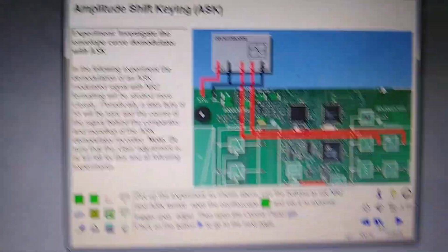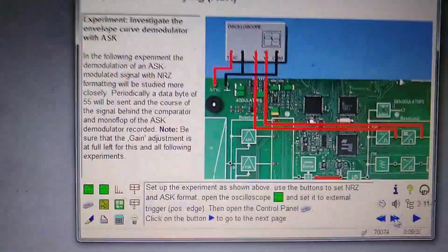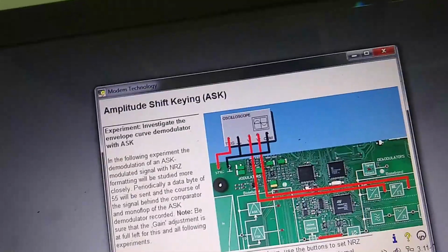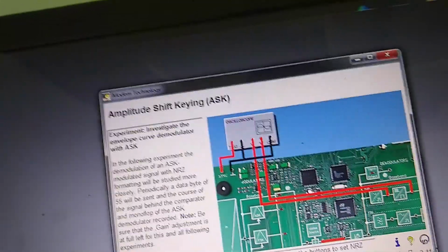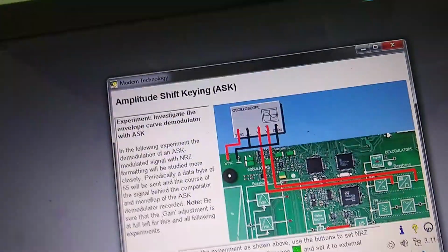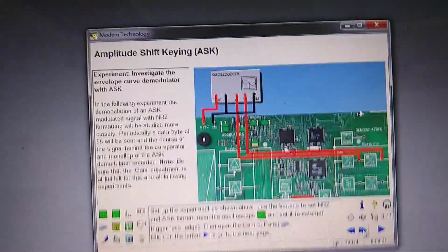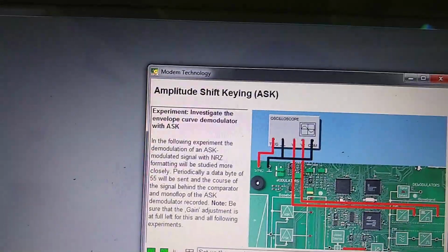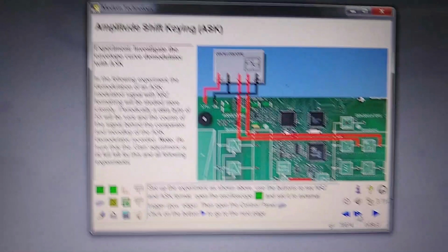So now, how much was our data spectrum? Data frequency was 0.6 kilohertz, and our modulated waveform center frequency was 9.95, and F0 plus FD, F0 minus FD. Okay, so now we will get back our original data spectrum with the help of demodulation.